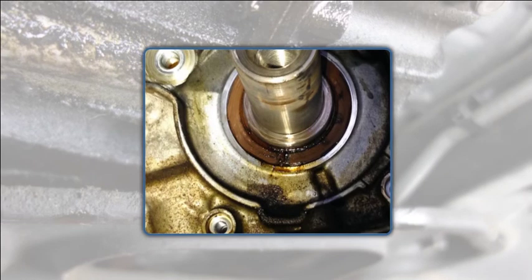Crankshaft and camshaft seal leaks are usually due to a worn seal. These seals can become hard and brittle, allowing oil to leak past the sealing surface. The seal can also wear a groove in the sealing surface of the component. This can be corrected in some cases by using a seal saver. Repair these leaks as follows.